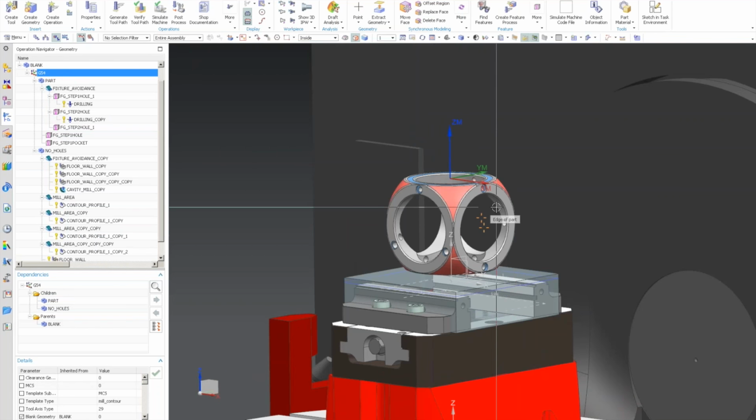All right, well, I wish I had more time. I could show some other things. I certainly will have more webinars. I wanted to show some deep molds. We tend to do some very deep molds with an 18 thou drill, and we just love the feature base for it because we're getting our holder within 7.5 thou of the mold.